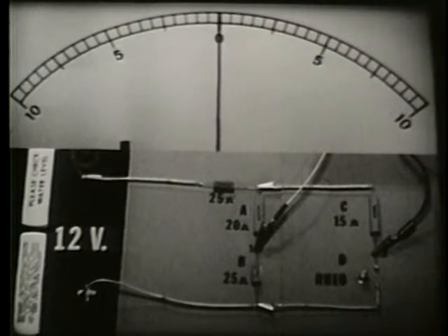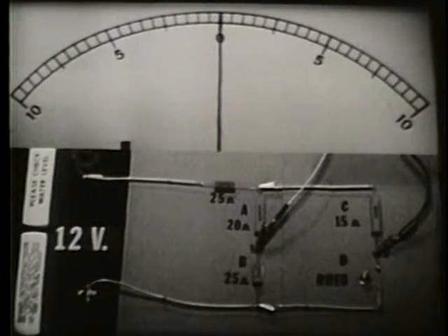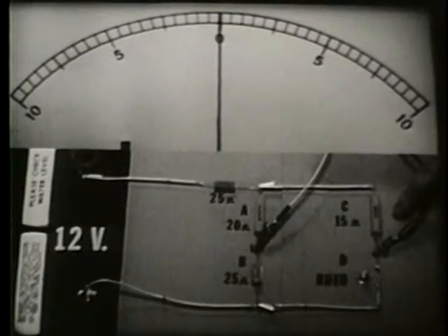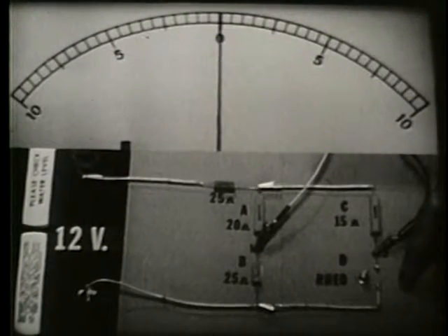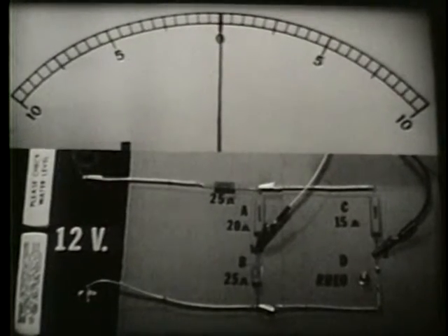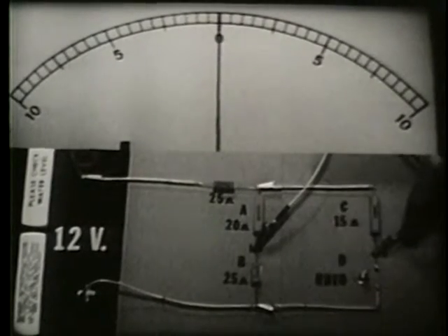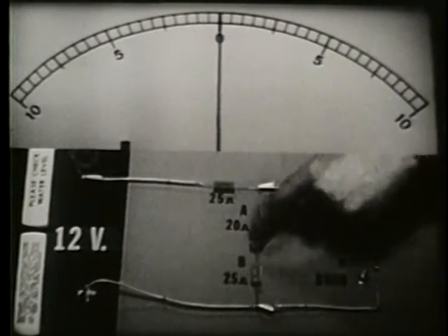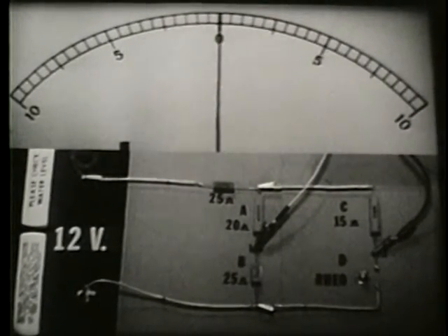This circuit is now a resistive bridge. And since points 1 and 2 are at the same potential, we have a balanced condition. Voltage A is the same as voltage C, and voltage B is the same as voltage D. In this condition, we call this a balanced bridge. Notice that the bridge is composed of 2 branches, and a detector circuit divides the branches into 2 legs each. Legs A and B form branch 1. Legs C and D form branch 2.